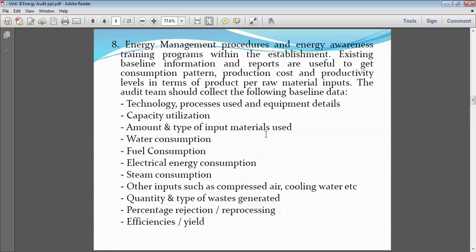I will give the example of our college hostel also. There are 5 HP centrifugal pumps, used to fill the overhead tank in hostel number 1. It required around 3 hours per day. Now we have replaced it because it was rewound 2 or 3 times. Instead of rewinding again, it has been replaced by a submersible pump of only 3 HP. So here the installed capacity has been reduced from 5 HP to 3 HP, and the working time also reduced from 3 hours to 2 hours only. So this is by adopting the new technology.